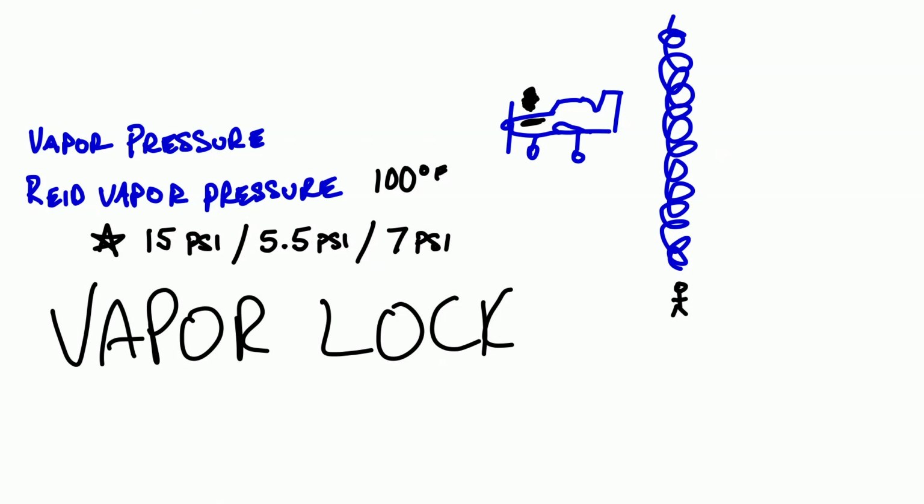So as the aircraft gets higher and higher and the air gets less and less dense, we end up in a situation where the engine can't take in additional air to compensate for the lack of density because the cylinders don't change size. It's as simple as that. And that's why we use things like turbocharging systems to increase the density of the air entering the engine, because we can't change the volume of air that the engine can take in and put back out. That's that volumetric efficiency that we talked about before.